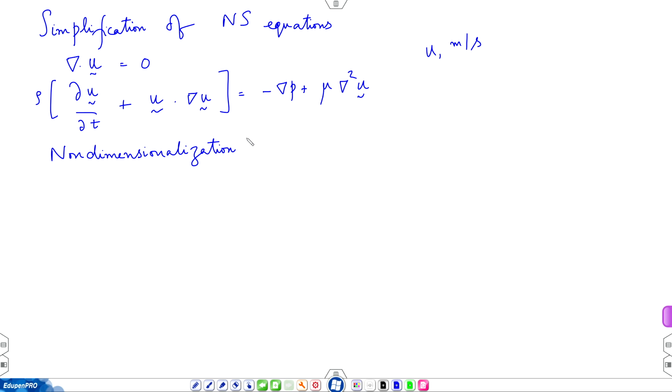But then if you cast it in non-dimensional form, the number of variables becomes much smaller. Friction factor is a function of Reynolds number and surface roughness parameter. So, non-dimensionalization helps you in reducing the relationship to compact form. You can think of it as simplification. We will also see that non-dimensionalization can be used to simplify Navier-Stokes equations in many other ways.